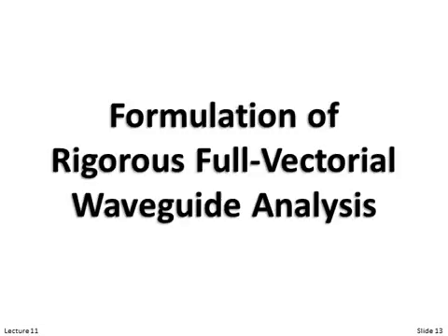Okay, so that is our brief introduction to waveguides. Now we're going to go to Maxwell's equations, and we're going to see how to pull all these together, use all the stuff we did with finite differences and the Yee grid. This is a really good illustration of how we can very simply formulate a really sophisticated code, and it's actually quite easy. And this is doing a fully rigorous analysis of waveguides. So no approximations will be built into this yet.